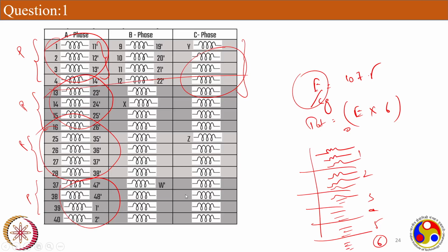What about the maximum current rating? In series, the same current would flow. If you want the maximum current rating, you need to connect in parallel. The voltage will remain the same. How so?